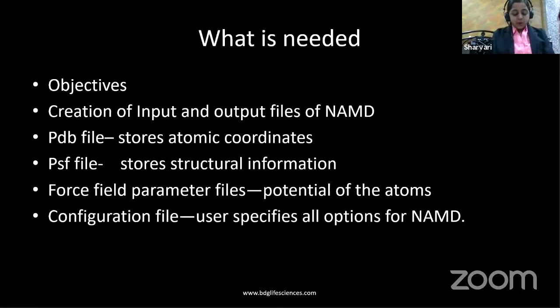The next is the configuration file. The configuration file is the file in which the user specifies all the options for NAMD. We are going to also see the standard configuration file. Most of the time you keep all the parameters as they are by default. The only difference is you change the time step according to your need. As and when you practice, you will understand what time step is required for the accuracy of the result.